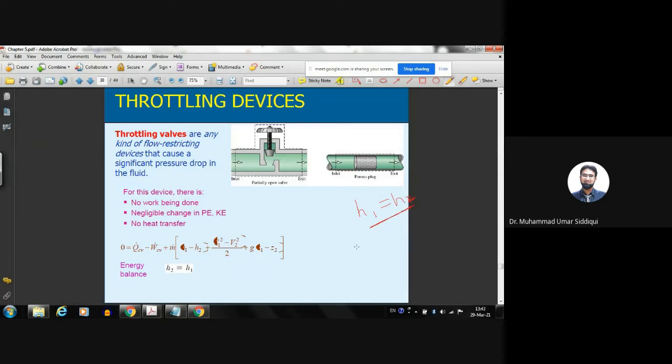But what happens is that pressure is significantly reduced. Okay, because outside pressure is the atmospheric pressure, and inside you develop the pressure by pulling the lever of the spray bottle. So the back pressure is significantly higher than the atmospheric pressure, and so there is a significant abrupt drop in the pressure. So enthalpy is basically what? It is internal energy plus PV.